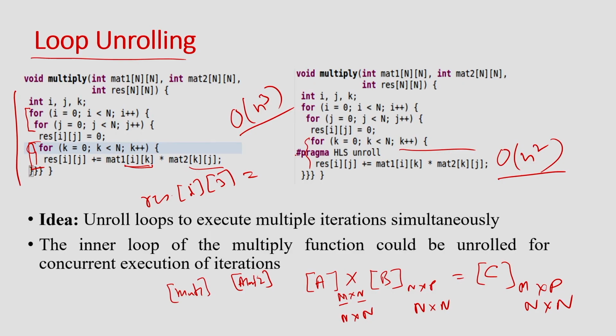Similarly, you can use unroll on the middle loop, right. So, instead of here you are putting it here. That means you are effectively unrolling both the loops. So, if you have an innermost loop and you put the pragma in the upper loop, that means both loops will be unrolled. So, effectively you need order of n time steps, because both loops will be unrolled, and that means for the i loop, everything will be unrolled, right. So, you need order of n time.